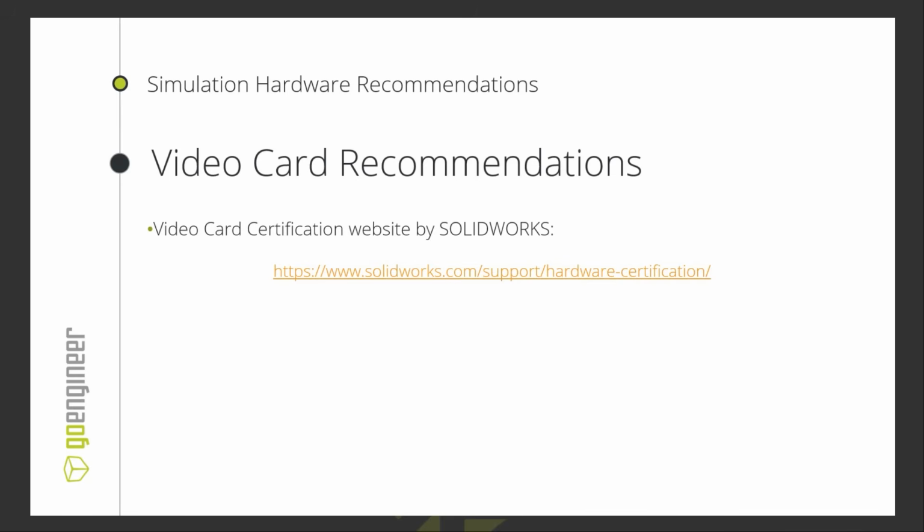It's an interesting comment. So the GeForce RTX 4060 Ti isn't the best. Well, for gaming, that's an awesome graphics card. But for SolidWorks, will it work? Absolutely. But that's a DirectX video card, not an OpenGL. GeForce is the gaming side of NVIDIA, not the professional workstation. So sorry, Ross.